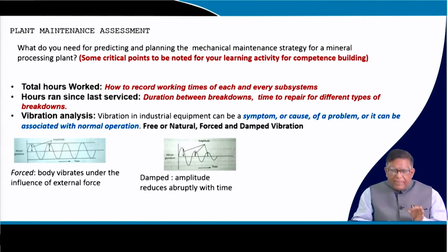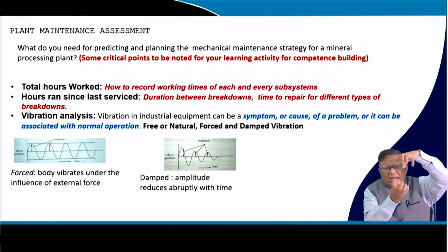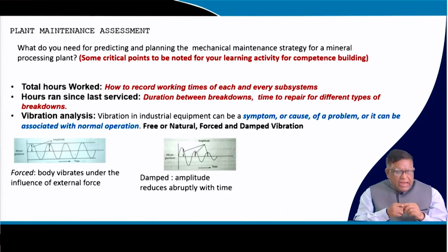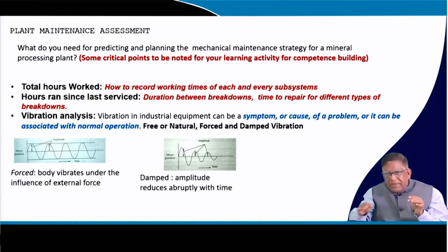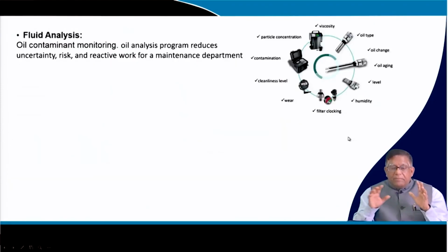To do that, vibration analysis and vibration study are there. Here again I will say you must know the different types of vibrations: forced vibrations and free vibrations. If you take a spring and it starts operating, that is free vibration. Now, if you keep a damper, then your vibration starts and it will be damping down, that is damped vibration. Now, this vibration analysis is important.